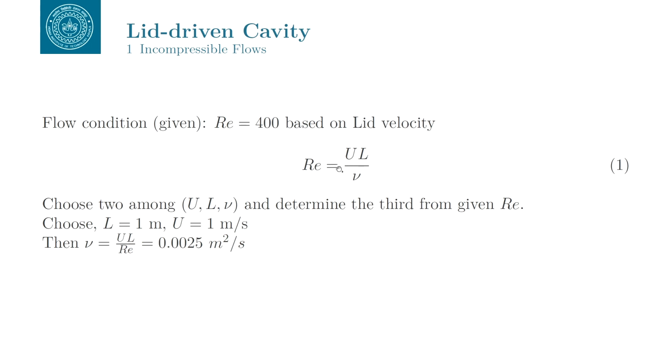Another thing you should know about incompressible flow is that the absolute pressure does not matter, what matters is the pressure differential. Unlike in compressible flow, where you have the relation P equal to rho R T and absolute pressure has a meaning, as we have discussed in the classes, in incompressible flows it is a mechanical pressure and there is no relation between pressure, density and temperature. Although the systems are coupled, what really matters is the pressure gradient and not the absolute pressure.